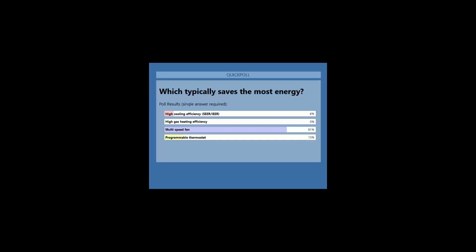So ways I can control it. I can have just one compressor and it turns on and off. That's what you have at your building now, very likely. Most of you have a single stage unit, it turns on and off. At your house, you have a single stage unit, it turns on and off. Most of you. It's pretty boring. It's not very comfortable. It does a crappy job of dehumidifying, but that's what you have.